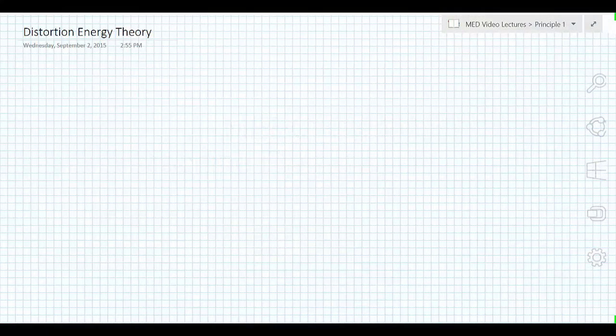Welcome back. In this video, we're going to go into a little bit more depth into distortion energy theory for static failure. The reason I want to do this is because we'll be using distortion energy throughout when we talk about fatigue failure, because it ends up being a very good way to average the stress from different types of forces. So we might have different amounts of fatigue wear from different types of loads, and how do you put those all together? Well, the answer is going to be by using this distortion energy approach.